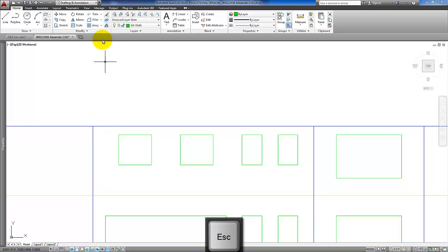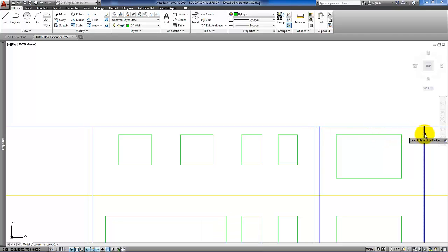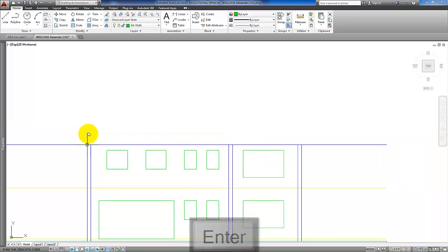The fascia will overhang at the side by 200mm. So let's do that on both sides of this part of the wall. And the other side, well, it's at a different height, but we can put that line in for now. And then we can draw the line up for the roof, but we don't know the height of the roof until we work that out geometrically on the side elevation. So let's make that layer current.